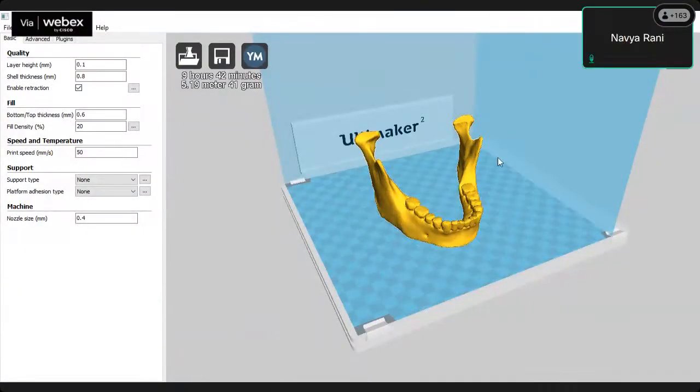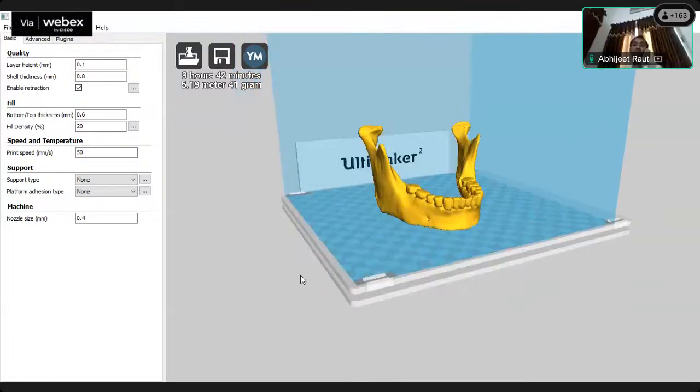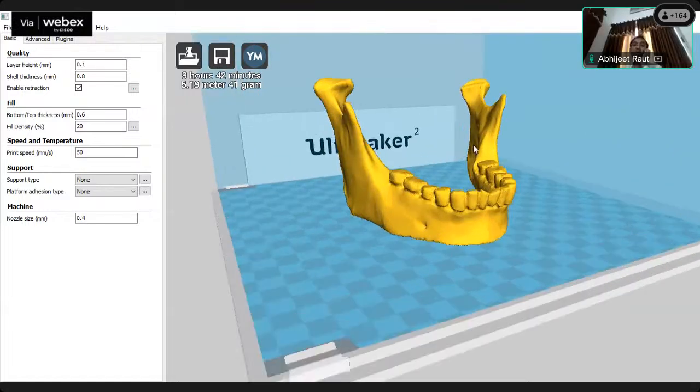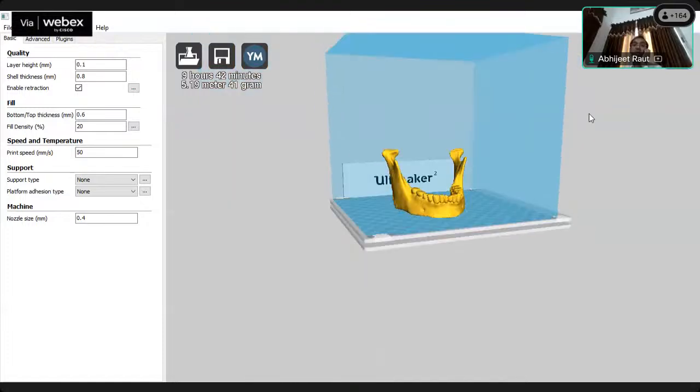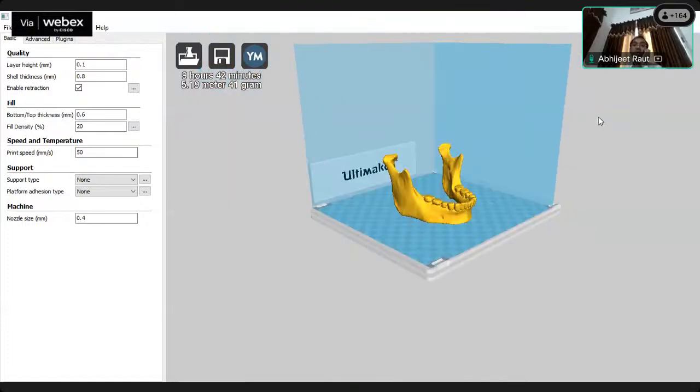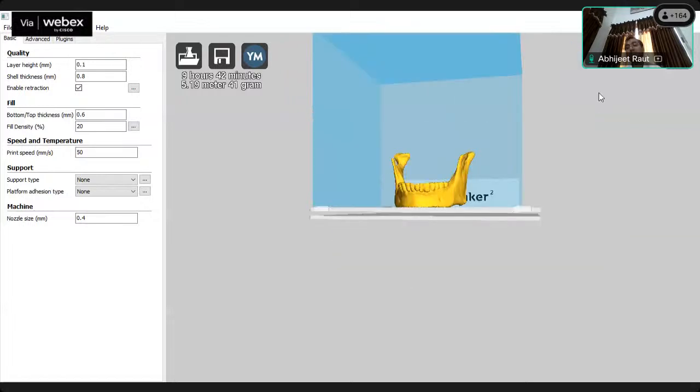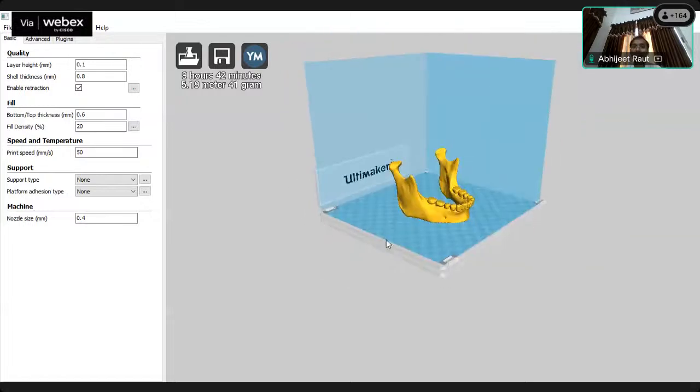Yes, sir. As I have given the introductory overview of that pre-processing tool, Meshmixer, another is 3D slicer. Why are we discussing this? To avoid those errors and issues while 3D printing. So with slicing software, we need to export the updated, corrected STL from Meshmixer into the slicer to generate G-code.